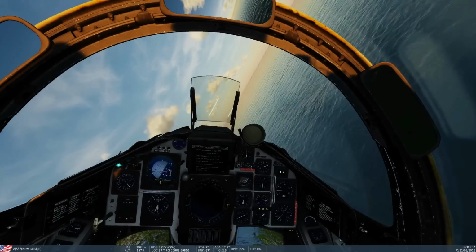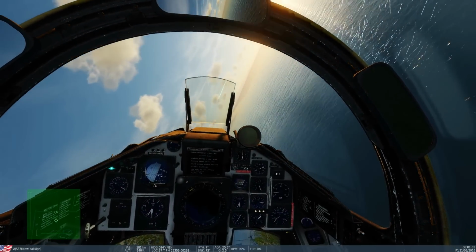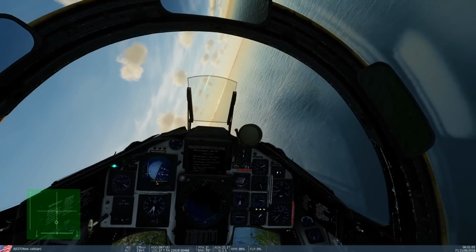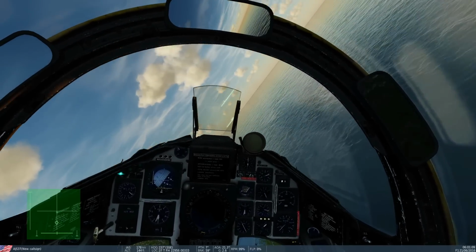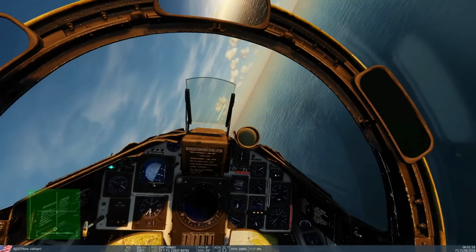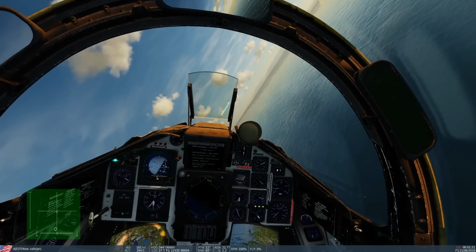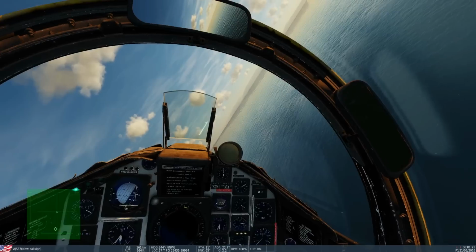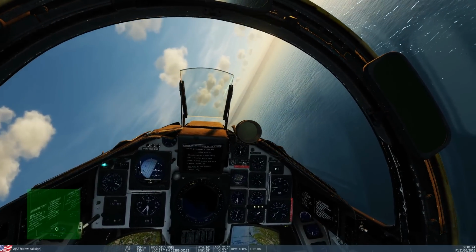I'm sustaining 20 degrees. Oh, actually, scratch that. Balancing the aft stick. I'm going to see if I can find the outer limits of SPARK. 21, we'll round up to the nearest angle of attack and try full aft stick. Okay, yep, SPARK's taking control at this point. I don't actually have control of the aft stick anymore. SPARK's limiting it for me to keep me from stalling, and it's decided that that's it there.